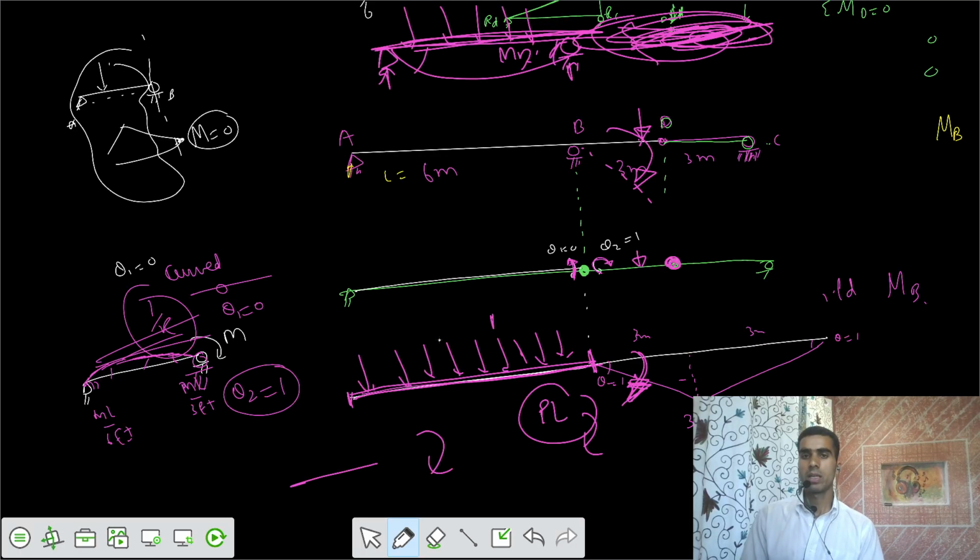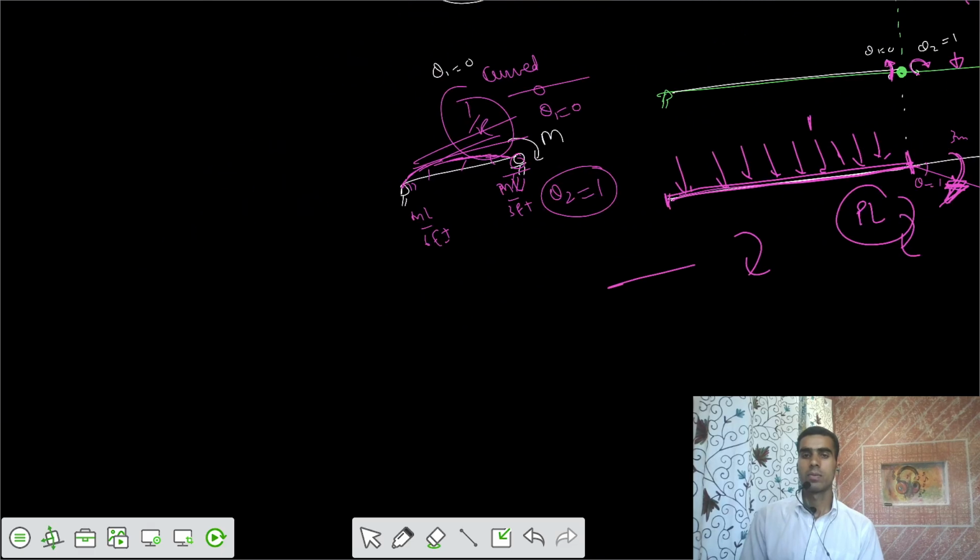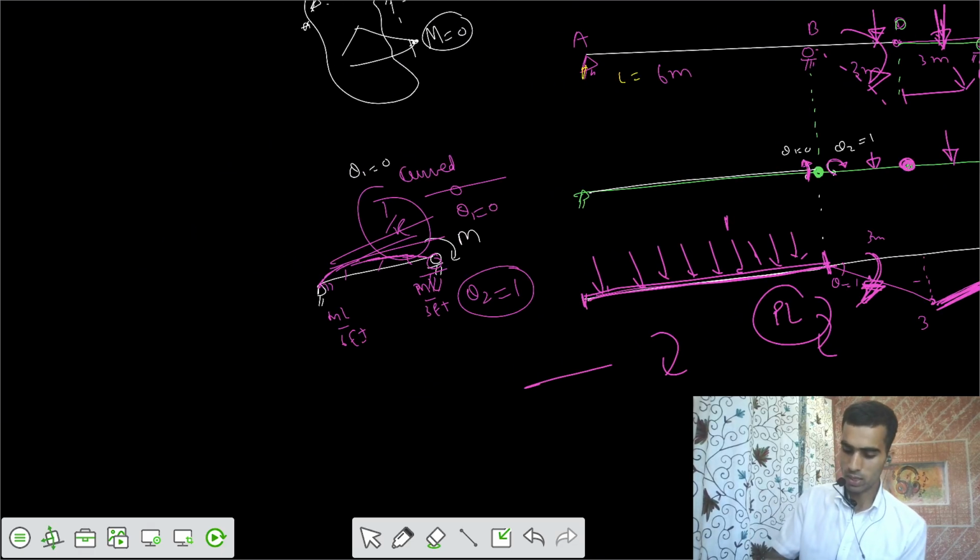Up to the point C, this is the variation, and if the load is somewhere here, let's say it was at this part, at 1.5, 1.5, that means out of that 1, your shear force would have been 0.5 here. The same 0.5 would be transferred to this point, and after that we can have a linear variation. Hope you got that.